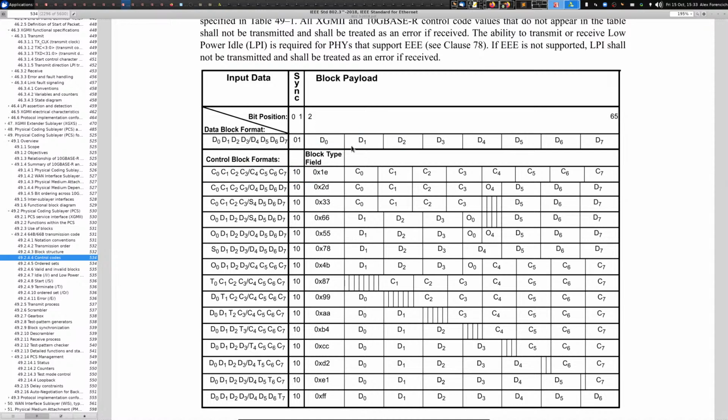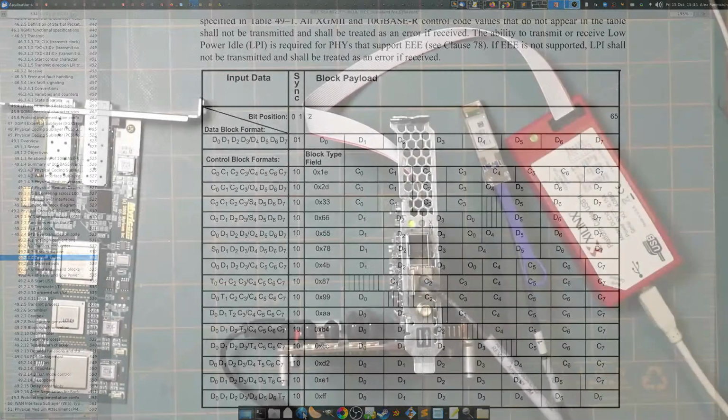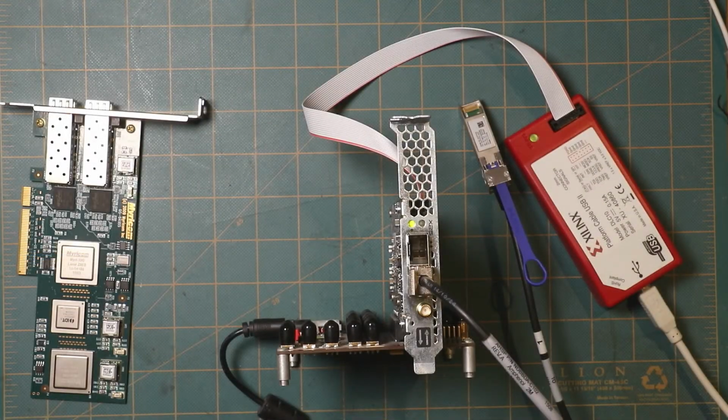But the other thing that line codes do is they give you some electrical characteristics as well. So whenever you have a high-speed signal, you're going to have to connect multiple components together, and when you do that, you have to deal with various electrical issues. So one of the things that's very common in some of these high-speed systems is you use AC coupled connections.